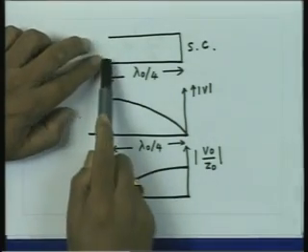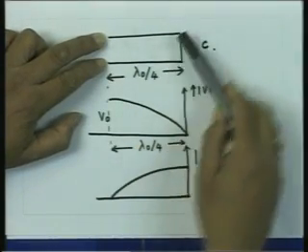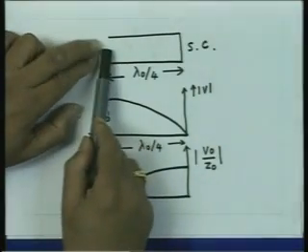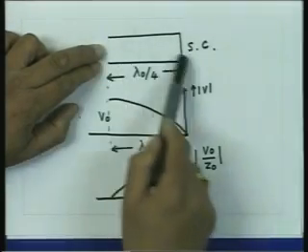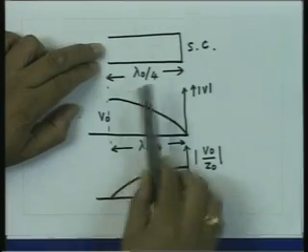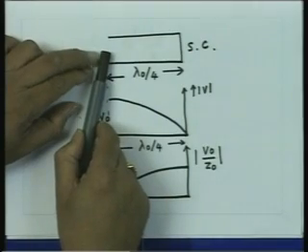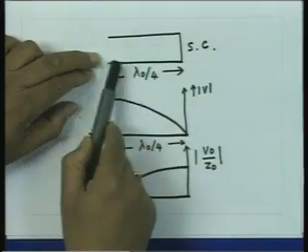So, if I find out what is the power loss at this location, this power loss will be nothing but the power lost in this line, because the line is short circuited at the other end. That means the load is not consuming any power. So, if at all any power is supplied to this, it will be only equal to the loss which has taken place inside the section of this line. So, without going into the primary constants of the transmission line, just by calculating the input impedance of this line, we can find out what will be the equivalent resistance to which the power is supplied, and from there we can calculate the loss of power in this section of transmission line. Precisely that is what we do now.